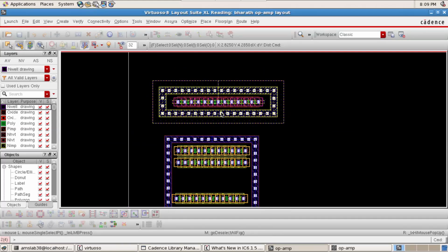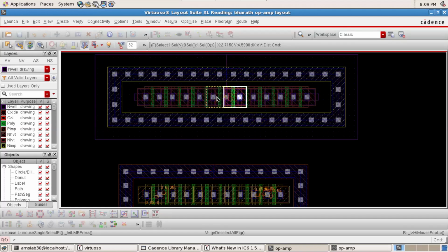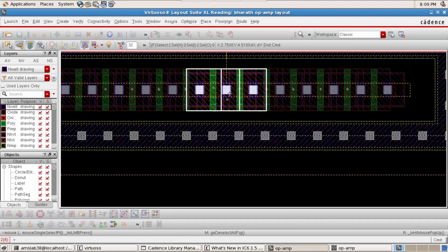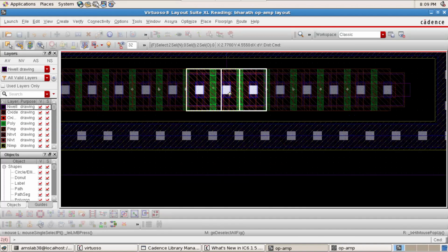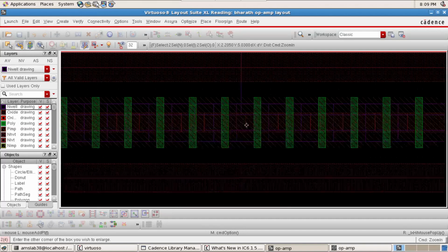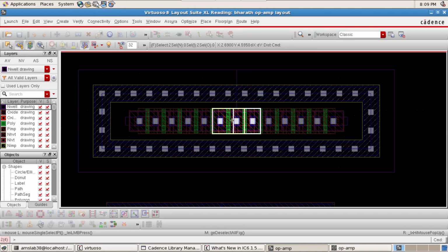Karthik, we have discussed interdigitization, common centroid and cross-coupled common centroid, correct? Yes, sir. Here, I have placed 2 diode connected devices in the center, which are commonly sharing one drain net. Okay, this is the drain net. If you want me to label it, I will label it for you. No, sir, it's a drain. I understand, sir. Drain is in the middle, sir. Center is the drain.